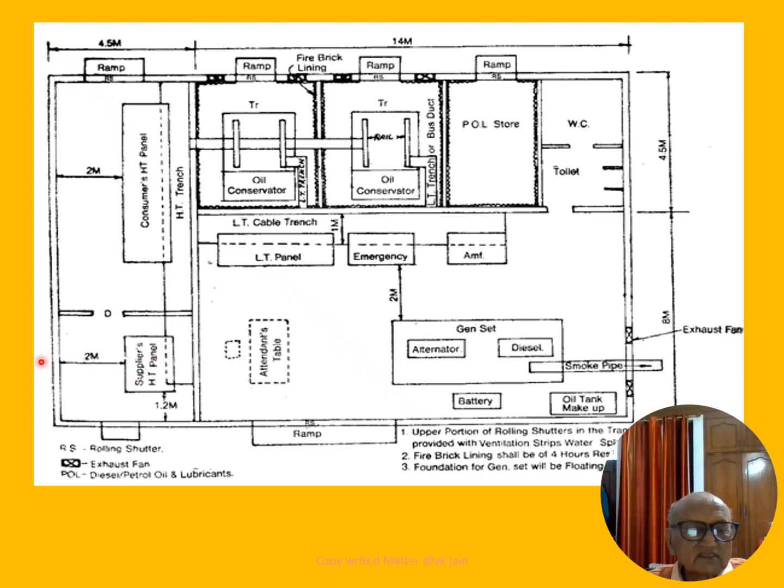So the electric supply comes through an overhead line coming like this, or, if the demand is low, up to 630 kVA, we may have a pole mounted system getting overhead supply from another substation, and from this pole mounted, double pole mounted transformer, we bring voltage in. Then next important is the ST panel.